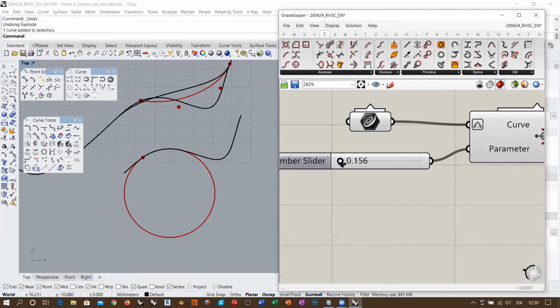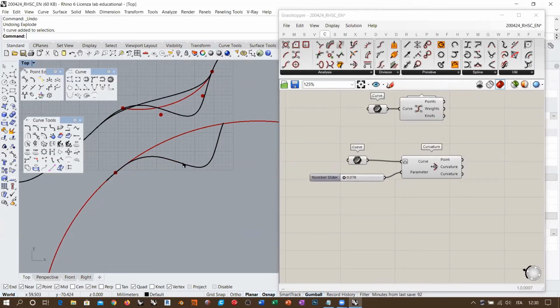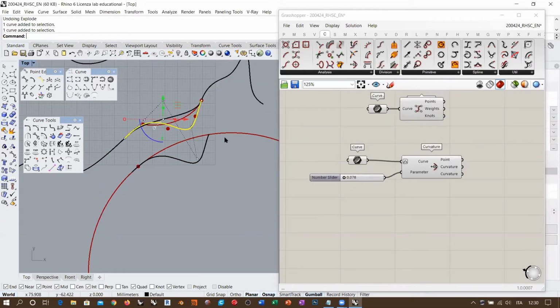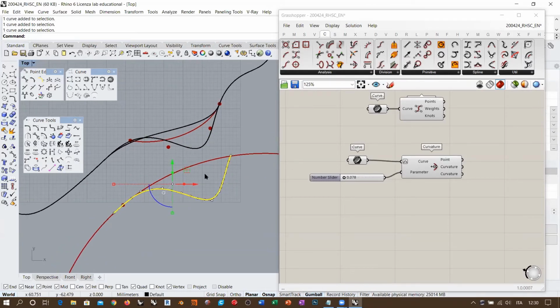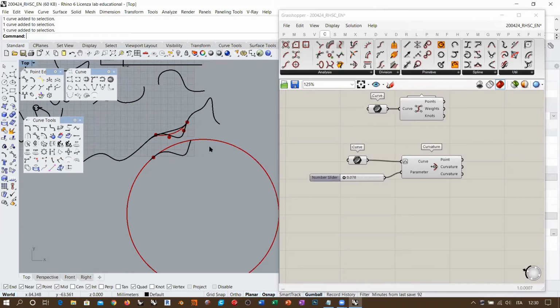You see that we change from one circle to another circle to another one, but they are constant along the path of one single segment, okay? So this is the difference between this blend curve and this arc curve. So you can regularize the NURBS geometry in order to make it easier to be produced or manufactured in real life. Okay, but of course you pay the price in terms of some deformation.